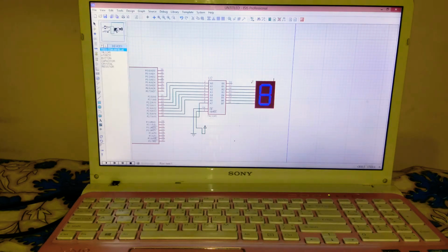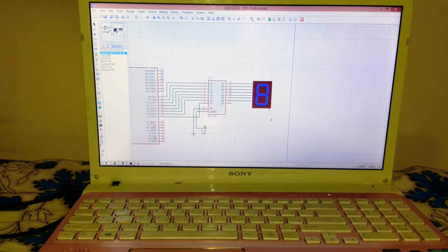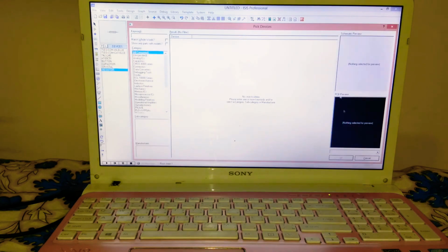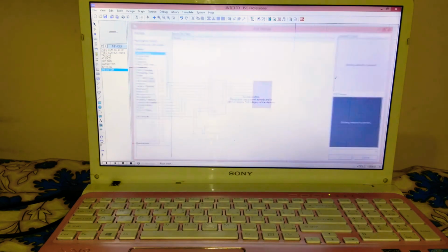Alright. So one will be left. So here we go. We connected each and every pin right now. So the 11th pin is vacant here, as you can see. So now we have to connect. So here we are using the common cathode basically. So we're gonna be connecting this, here we go, to the resistor which we had here, using that resistor to the ground.